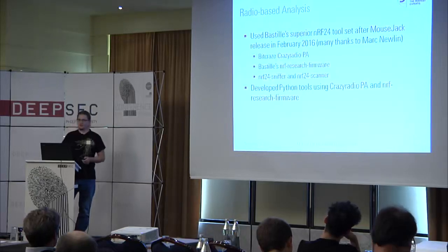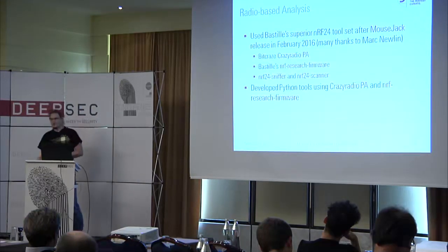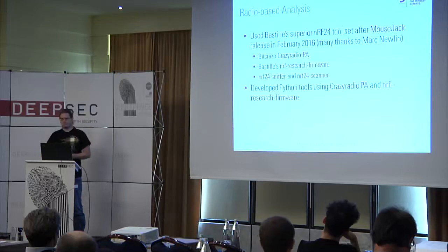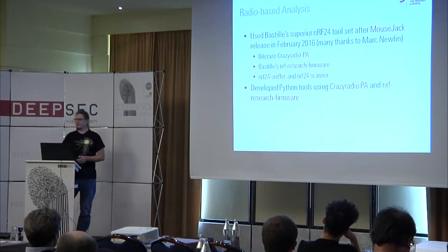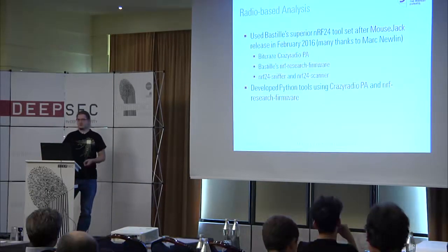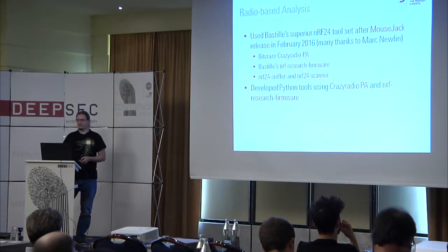We later changed to the set that was released with the MouseJack attack. They did some similar research to ours, and they're also targeting NRF24 chipsets, and it turns out it's way easier to just use the chip itself, an NRF24 chip, to talk to another NRF24 chip than using a software-defined radio, and that's what they did.